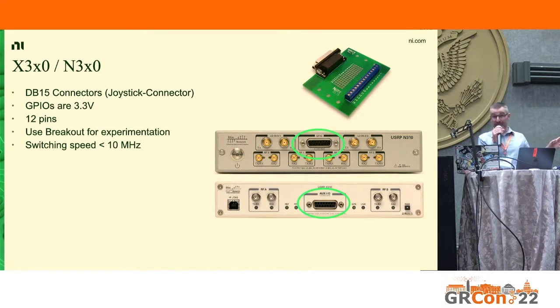By the way, I didn't put this on the slide because I didn't want to, but if you're in a pinch, you can just put the jumper cables from a breadboard straight into the DB15 connector, but please be careful. Okay, that's not recommended operation.